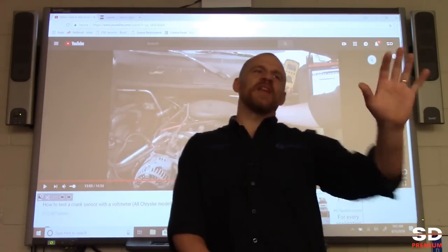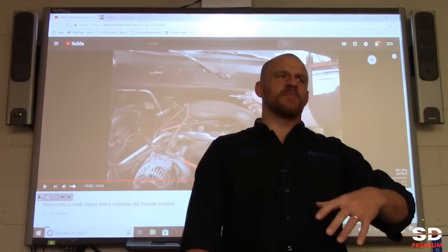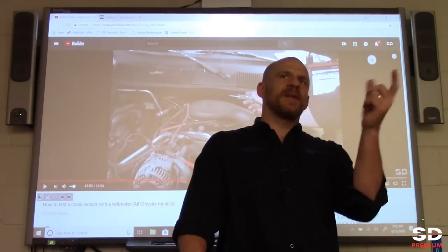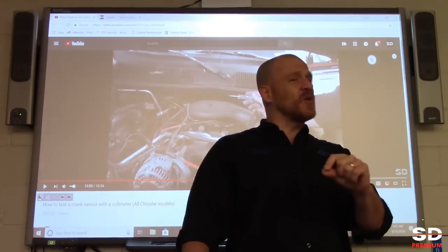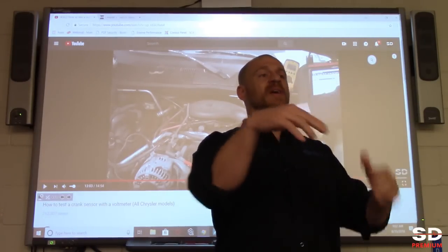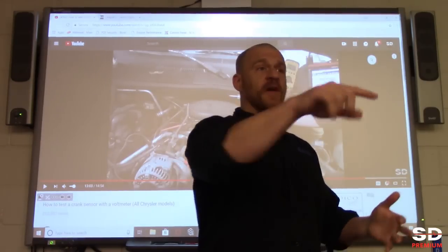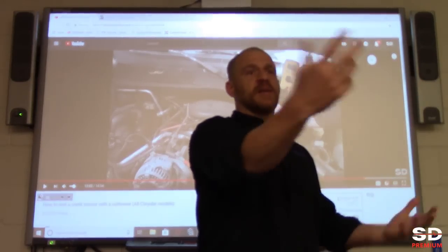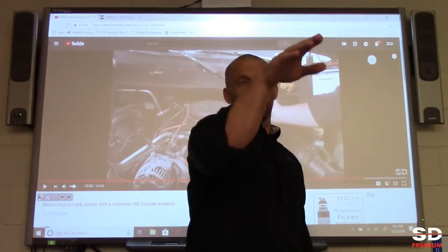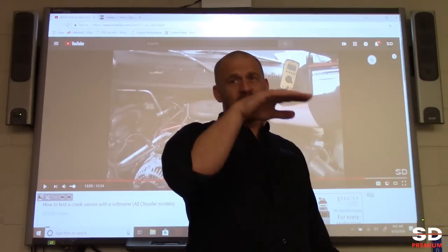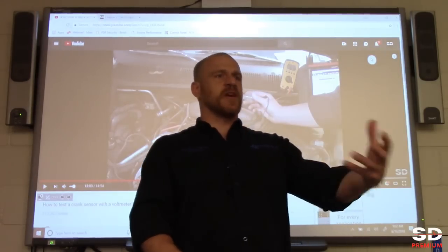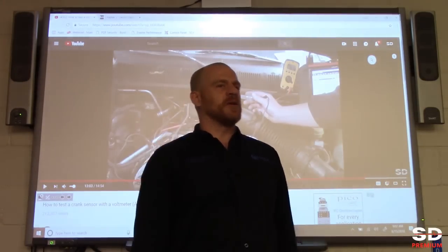So that's more of an output side that you just mentioned, Bryce, and we're talking about the input side. Now, if we're talking about an AC request signal, that's a little bit different. It would say AC request, yes or no, and that would be solely based off the button on your dash that says AC. So that would be the input side. But the one you mentioned, when it says AC clutch, yes or no, that's more of a command than it is an input.